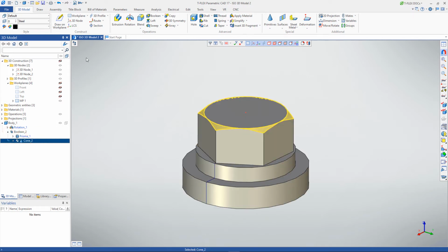Let's roll back this action to see another way to create a Boolean operation. You need to select the body, in this case, body 2, hover the mouse, press the left mouse button, hold and drag and drop on body 1. Thus, you create a Boolean addition operation.